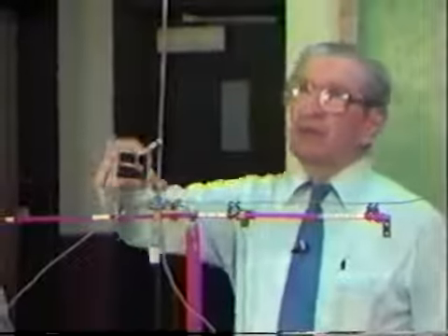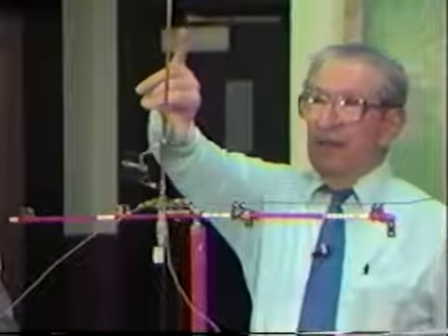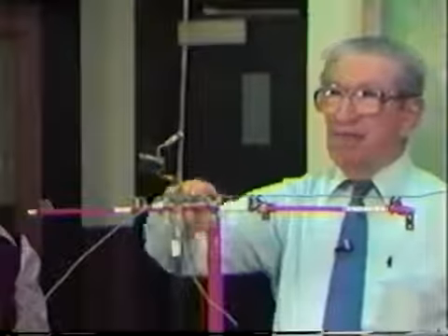They are acting as a reflective surface so that this quarter wave antenna is seeing its image by virtue of the ground plane wires, and this termination that we have from the coax line is now looking at a resonant antenna and being able to radiate the power, accept the power. Before, when I had these radials off, it would not accept the power.